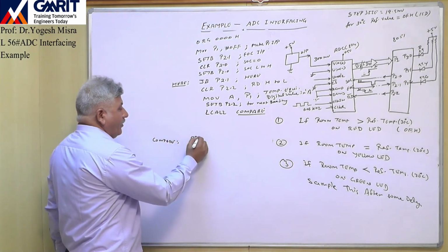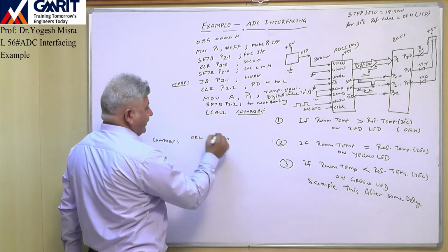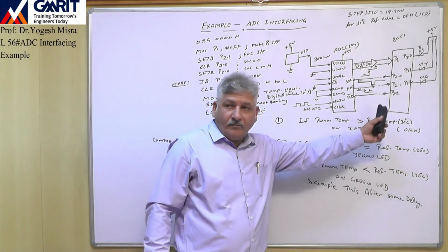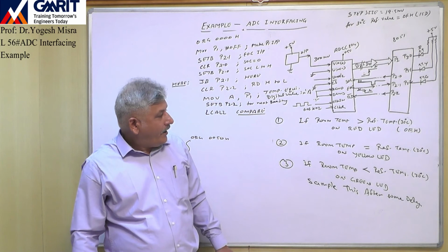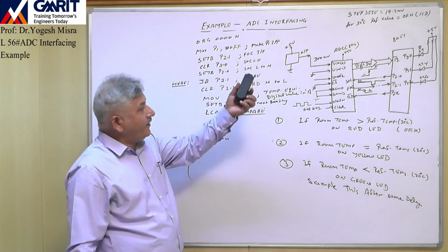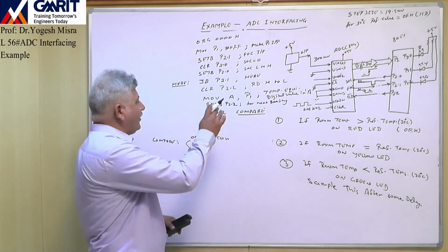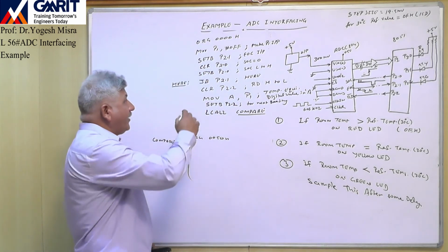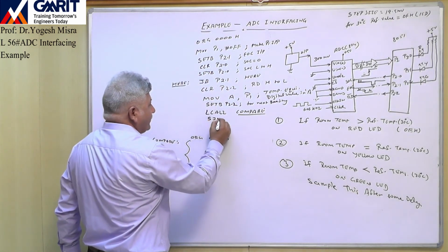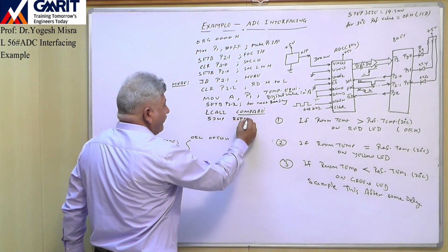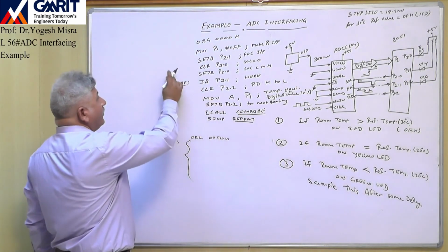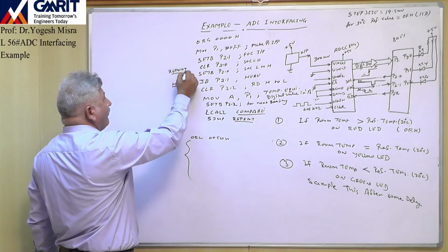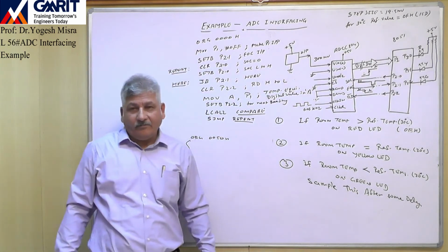This and this ORG 0050H, right? So here we have written the logic for verification of this. And after the verification, a certain LED will glow, and finally the program will come back to this point. And once it comes back to this point, we will repeat the process. So here SJMP repeat, and repeat will be from here.